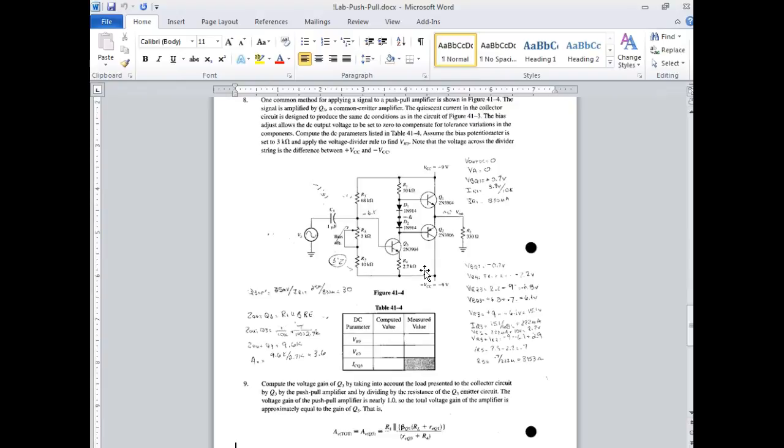So basically what you do is you start with 0. Ultimate goal is to get this right here at 0 volts AC, or 0 volts. We want this guy to be biased at 0 volts because we want them to be Class B amplifiers, right? What's a Class B amplifier? 180 degrees. So what we want these things to do is I want exactly 7/10 of a volt right here and a 7/10 of a volt right there. So this will be a positive 7/10, this will be a negative 7/10, which would set this guy right here at 0 volts.